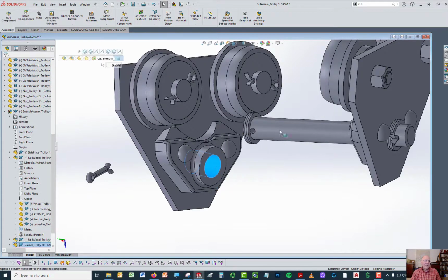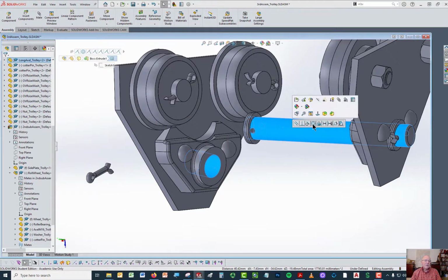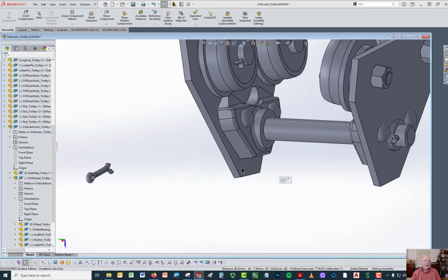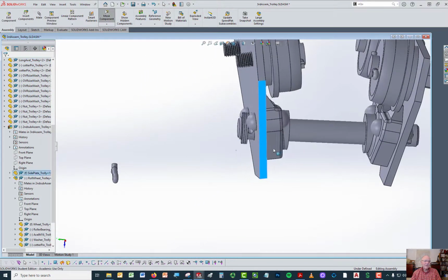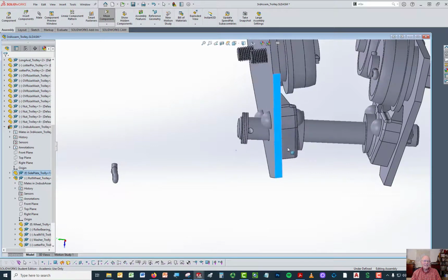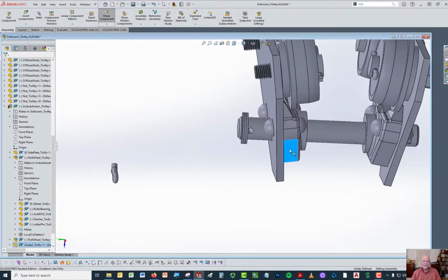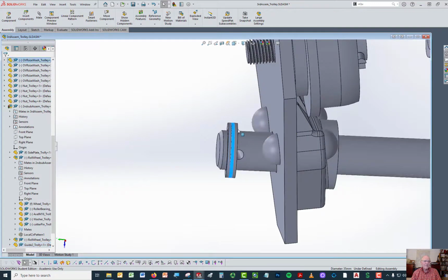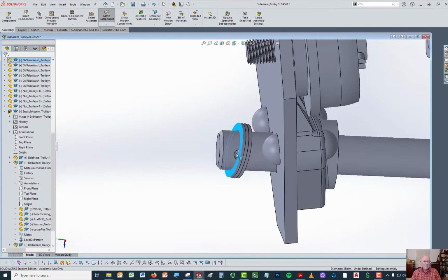Now, I'm going to make a concentric mate between the shaft and the hole of that, which is exactly where that would go. Now you notice this is free to turn like that, which it would be if we were assembling this in real life. It wouldn't be controlled by this because there's no relationship between them. I'll bring those washers over here. Let me just bend them.